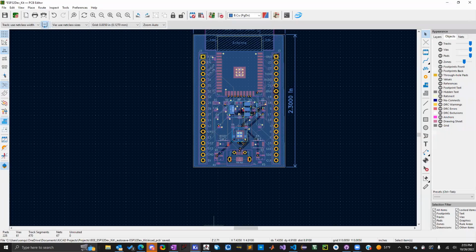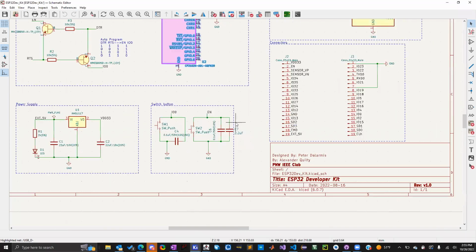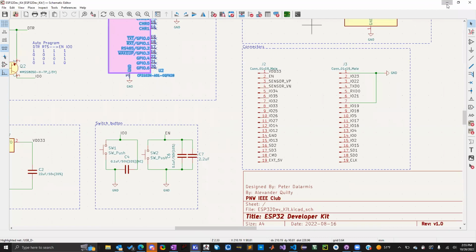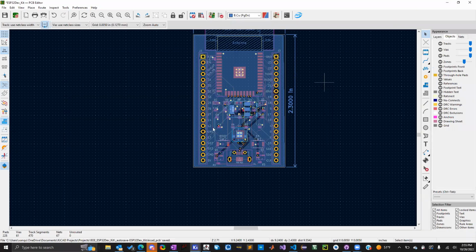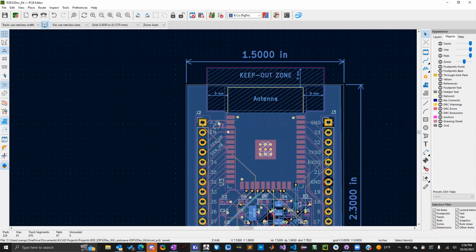I don't know if you guys got this. I had you add the extra capacitor here on the enable pin, right? Yeah. Okay, cool. That was a problem with the actual dev kit that we found on the forums, because it was related to my senior design. It had to do with the auto boot functionality in the ESP32, so that capacitor should help with that. I thought I'd add it because it might make your life easier sometime.